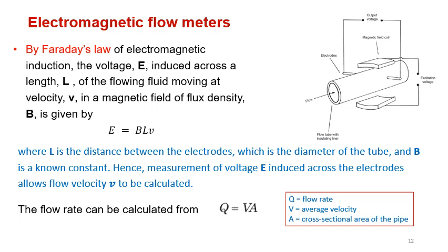The electromagnetic flow meter depends on Faraday's law, so we consider Faraday's law while thinking of it. What does Faraday's law say? If there is a magnetic field, with south and north poles, and a conductor cuts the magnetic field, I mean it moves up and cuts the field while moving at a certain velocity, there will be voltage induced in this conductor. The voltage induced in the conductor is calculated from this formula.